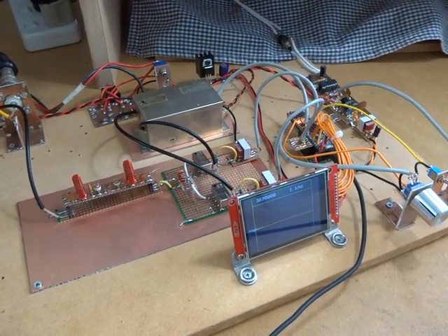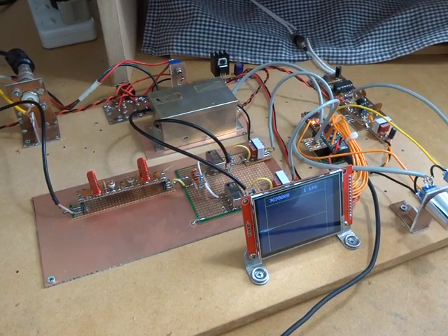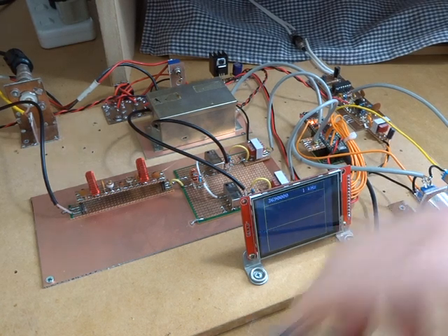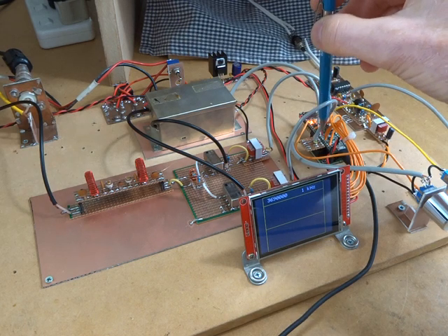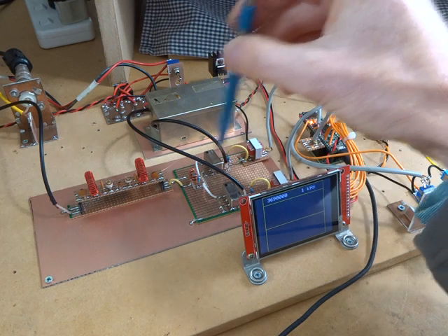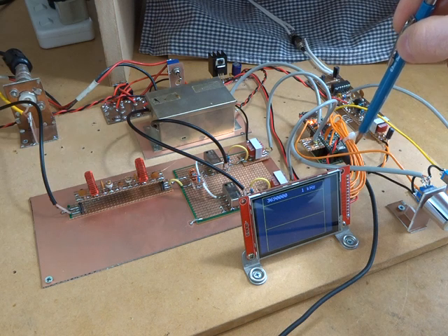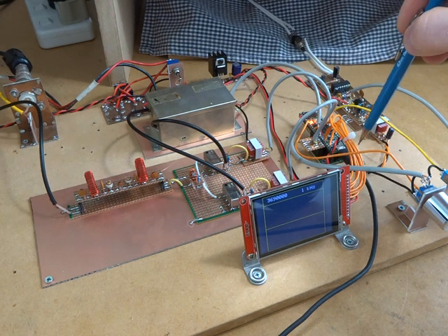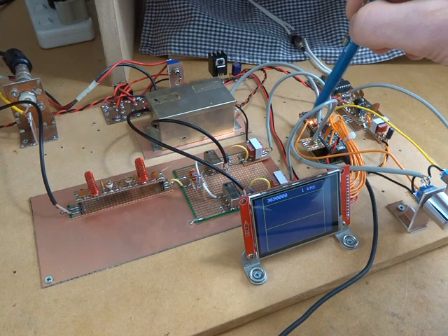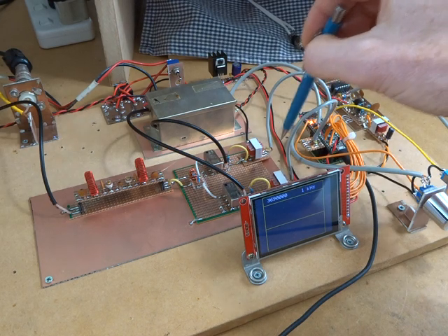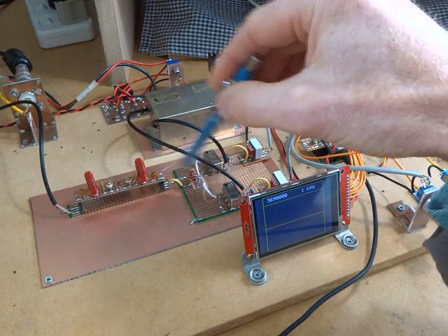So moving forward from here, I might convert now into a transmitter. For that, we're looking to use the line out of the audio panel there, and feed this thing backwards through the system. So the microphone input to the audio panel will be the microphone, funny old thing. We'll then feed it through the DSP in reverse order, and like I say, pop it out the line out and feed it back through here. So it'll be mixed up to our desired frequency, combined there, and out she goes.